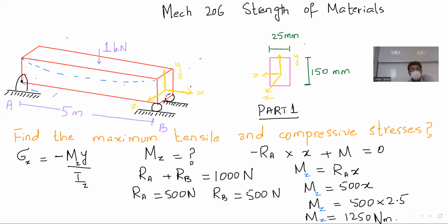Look at it like this, right? So the fingers of the right hand, right? So thumb is pointed towards me. That's how the beam is bending. So it makes sense that the moment being created by this load is in the Z direction. So this is surely MZ.